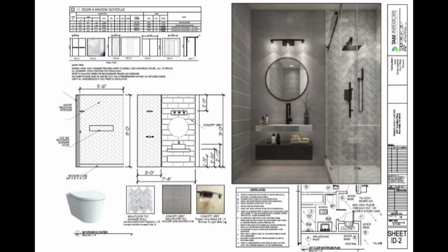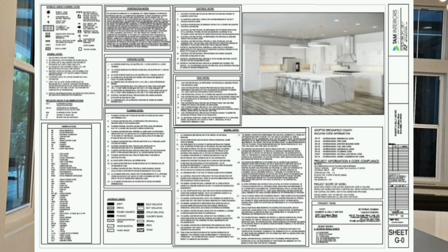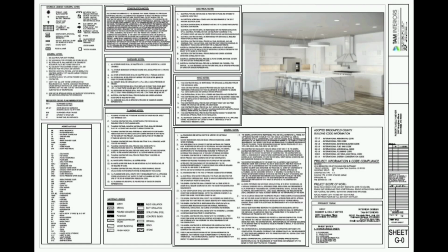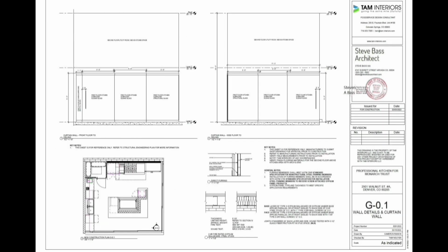and accountability. Think of this phase as creating the instruction manual, the blueprint for the general contractor, subcontractors, and permitting authorities. Every decision made in concept and design development phases is now translated into a coordinated, detailed set of documents that serve two essential purposes. Number 1, obtaining building permit. Demonstrate compliance with building codes, zoning regulations, accessibility law, and safety standards. Number 2, guiding construction and bidding. Provide contractors with clear, detailed information to prepare accurate bids and to build the project precisely as intended.